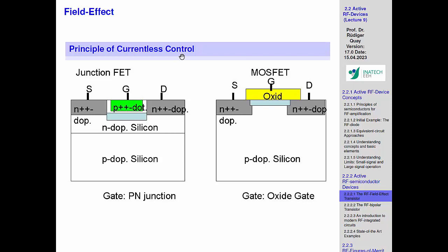So, for example, one thing which is very important there is that we could also make a FET without that MOS. We could also take a junction, so we could take a PN junction in here. Why don't we like that? Just based on what I just showed you with the RF control. What is your answer there? What is the principal advantage of a MOSFET? Why is it good to have this MOS diode there instead of some junction diode?